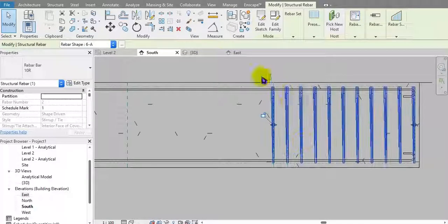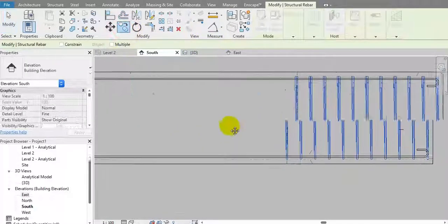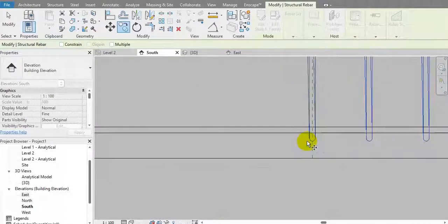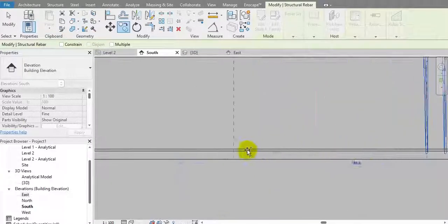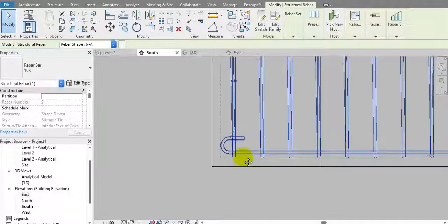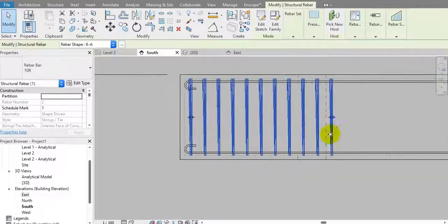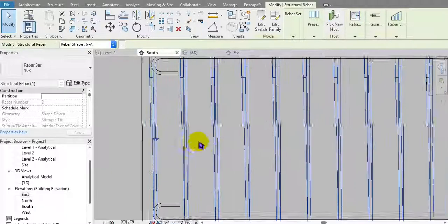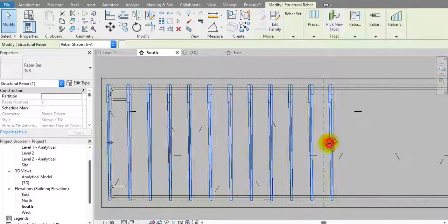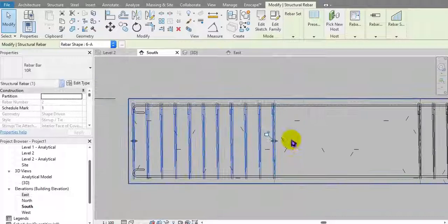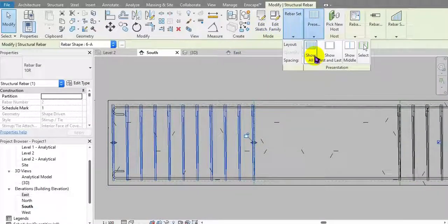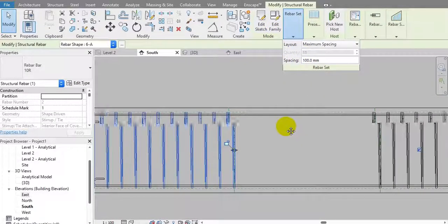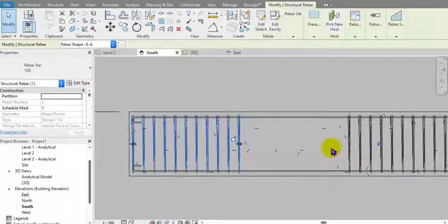Alright, okay, cool. Then you can copy the bar from the first point, it will stay right here to the cover, and one can be right there. Okay, all these will carry a spacing of 100 millimeter, and in between the spacing was restricted to 200 millimeter.